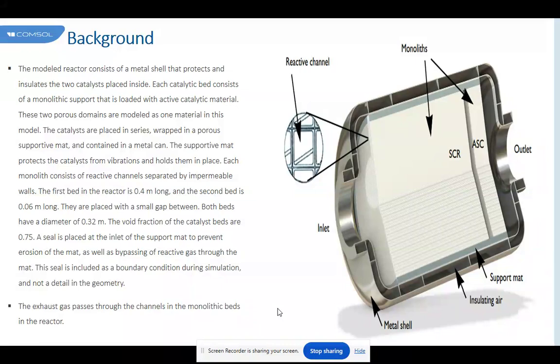In the core region, the reaction rate starts high, then it progressively decreases until full depletion of CO. It can be seen from the equation that the denominator in the rate expression is close to 1, and also that, given the inlet composition, YO2 is almost constant. Hence, the main factors driving the reaction rate are temperature and CO. According to this simulation, the former is comparable in the four cases, so the latter dominated the reaction rate among all of the other parameters in the rate expression.